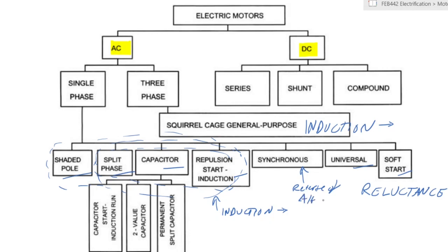In many cases, actually, synchronous motors and synchronous generators are the same machine. That is, the operation of the machine depends on whether you are inputting mechanical energy or outputting mechanical energy. That's the only difference in the machines, because they have a field winding being rotated inside an armature, right? So at that point, that's the brief introduction of motors.